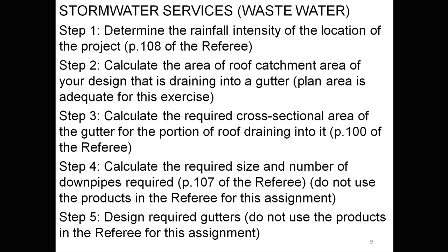And now we're in a new rain pattern, so everybody is really going for much worse scenarios. If you're really worried about it, then use the rainfall intensity from Cairns, which is what I tend to do when I design box gutters.